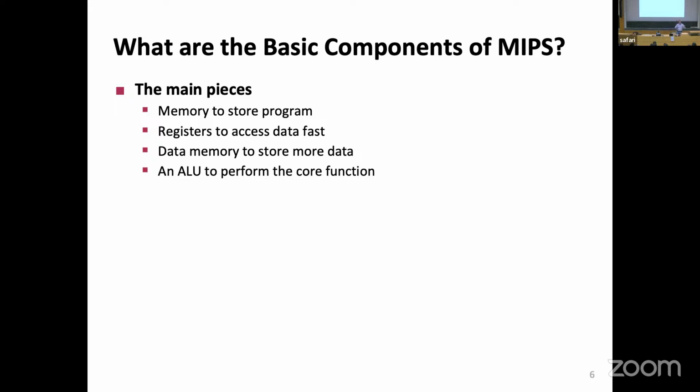Those are modules, they have inputs and outputs. They are connected one way or another. And most of the time, there's a multiplexer allowing you to have a choice between, let's say, taking this input or another input, or taking it from here or from there. And those control signals all come based on the decision when you make the instruction decoding. You take a look at the instruction. The bits of the instruction tell you what type of operation we should be doing.